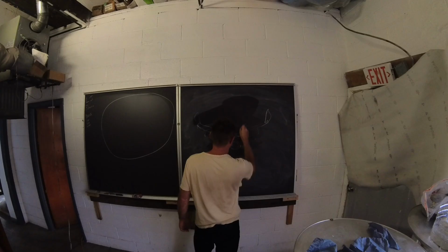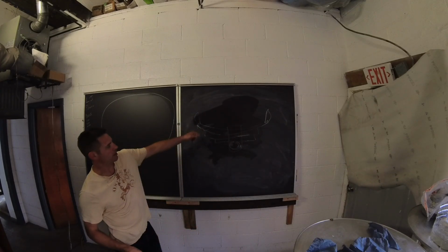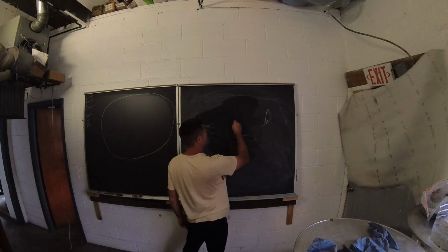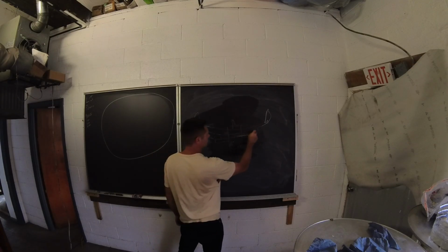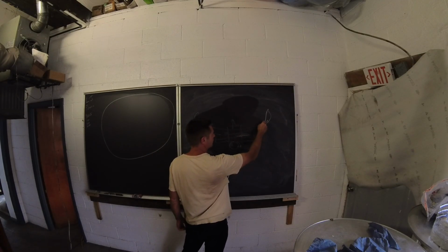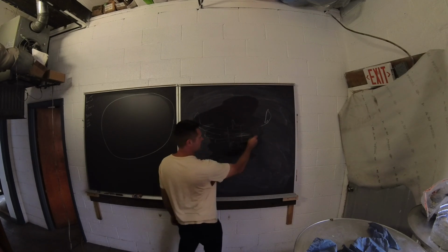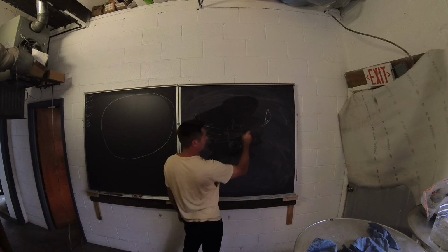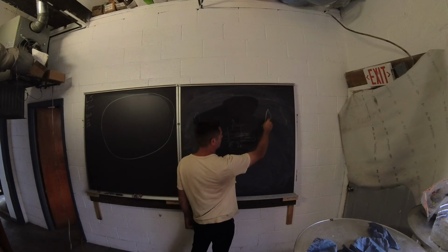And there's your axle and your axle hangers. So with a leaf spring, when you first start moving up, you're really not flexing these 2 springs, you're only flexing the 1 spring. Because you have appreciably thicker spring mass with the extra 2 leaves, most of your flex is just in this one little leaf.